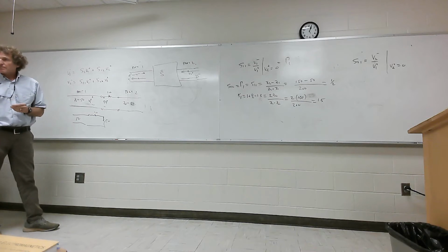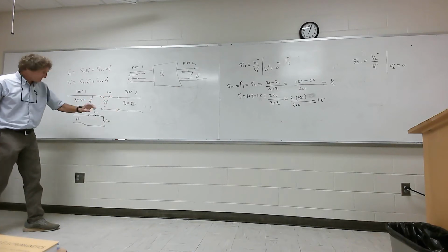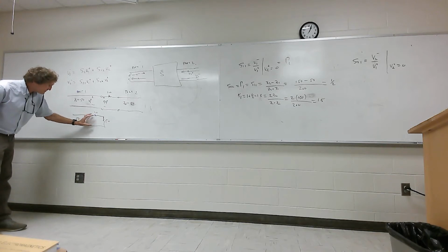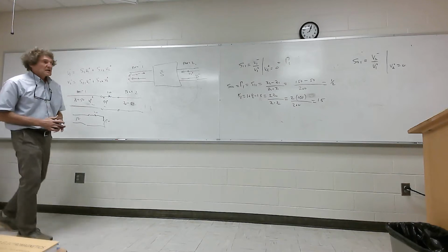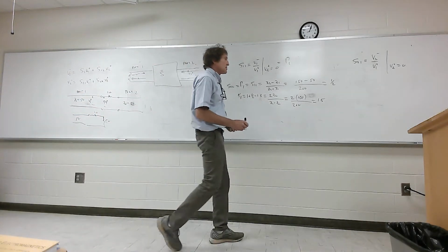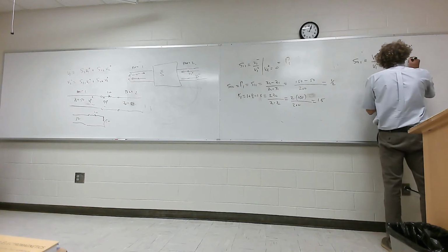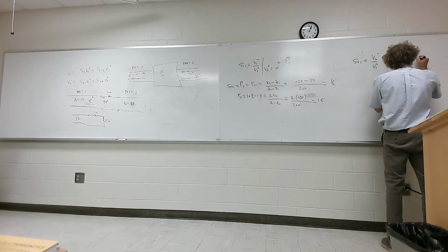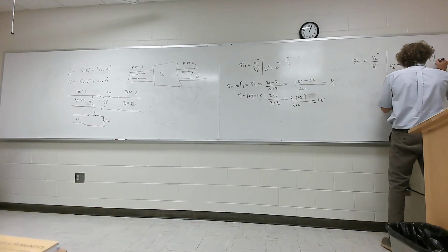Everybody okay with that? Can you all appreciate that? Now of that, not all of that gets out. What happens is there's voltage division here. You all see that, guys? Think of the voltage here as now divided. So it would be divided by 50 over 150. So that means when I actually look at this quantity right here, that's going to be equal to the transmission coefficient, right? Then it's going to be times that voltage division, which is 50 over 150, or 1/3.